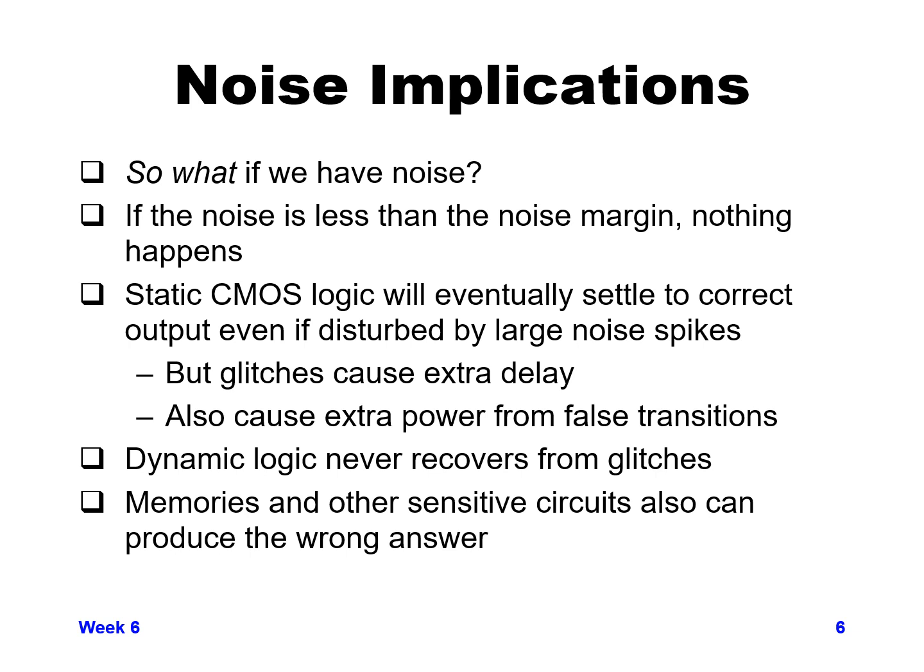But keep in mind that if you have a glitch that can propagate through the receiver stage, it will in effect either cause extra delay or it will cause a switch at a time when your timing tools aren't actually searching for a change in the value of the signal. And so it could cause something to switch at a time when it actually will get captured in a downstream latch or flop as an incorrect value. So that's the most problematic.